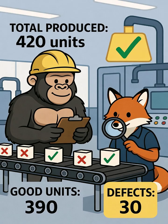Let's say you produced 420 units during your shift. Out of those, 390 were perfect first-time quality, but 20 units had defects and went to scrap, and 10 more units needed rework before they could be shipped. Your quality score is 390 divided by 420, which equals about 93%.